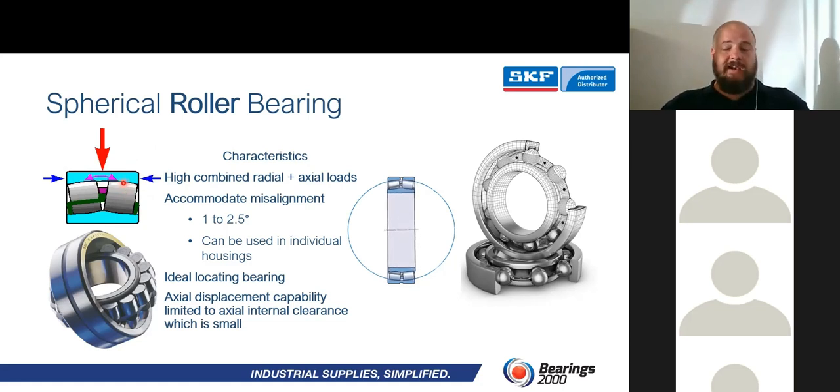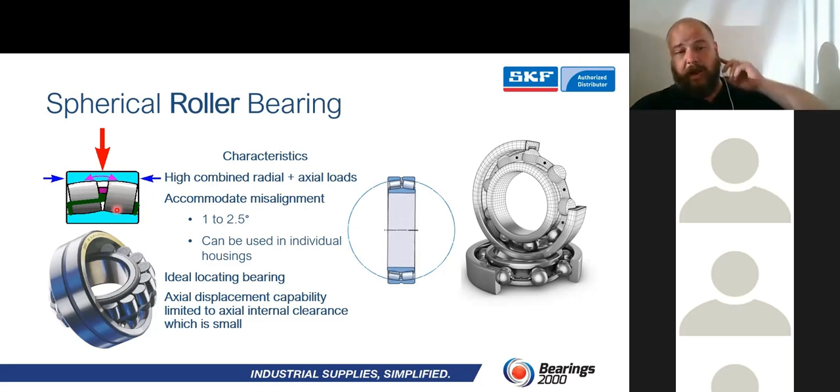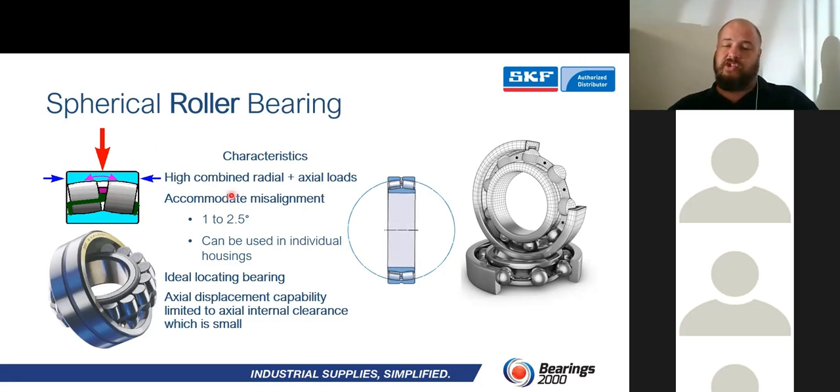Once again, guys, I need to state the fact that it's not there for misalignment. It is there in case you do develop some misalignment down the road. Ultimately, you need to make sure that your units and machines are aligned appropriately. But as you can see over there, that little nice animation shows how the bearing would be moving within itself, making sure that we do not exceed the capability or the maximum, having it run outside of the raceway. Okay.